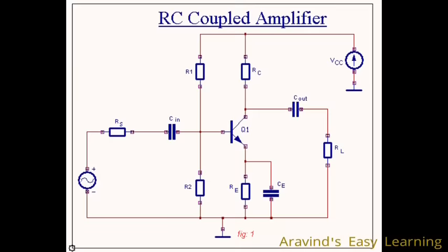That means, look at the circuit, here, here, here, all these capacitors, their reactance is increasing. So instead of acting as a short circuit for the input, and here also we need a short circuit, now it's acting as a resistive element that produces some resistance here.